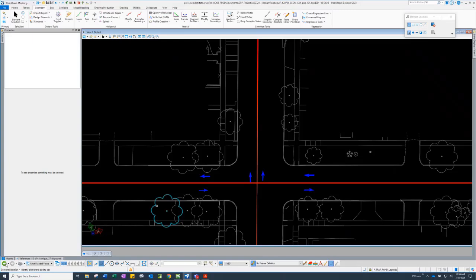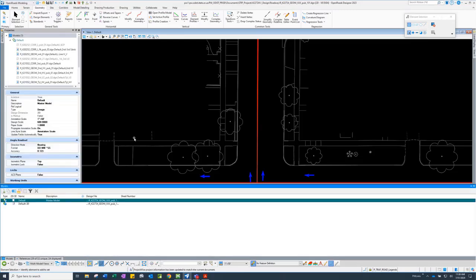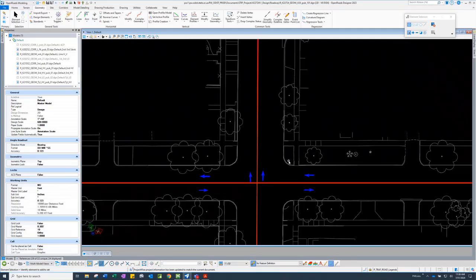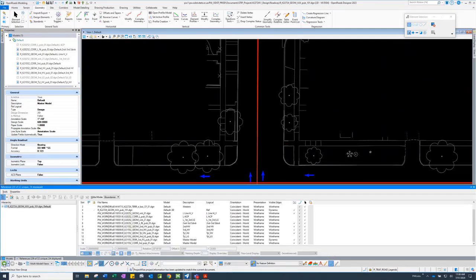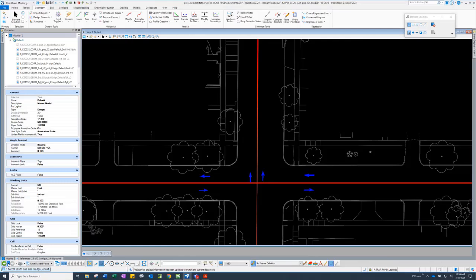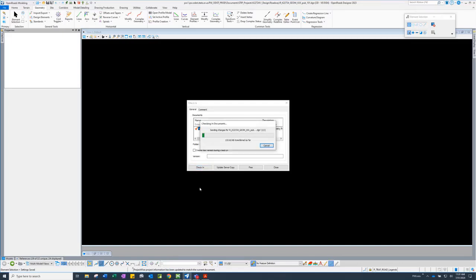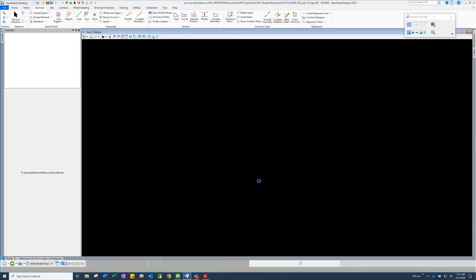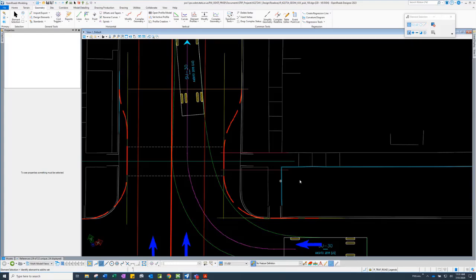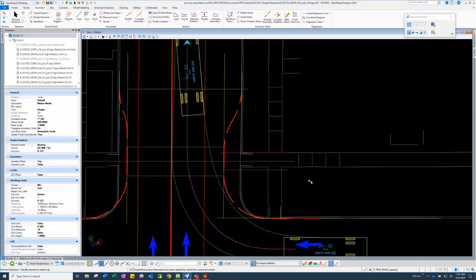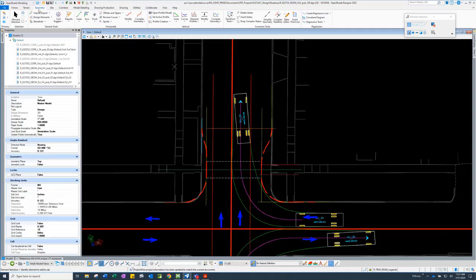And we see in the lower left corner a green circle with a white back arrow. If you click that back arrow, you can also choose, there's a pick list that's available if you go more than one, but most designers I know will do one change and that's about it because of resources of your computer. Anyway, hit the back arrow and see what happens. It will prompt you to check in the file that you just opened or free it, and it reopens the original file. Now, one of the things to note is I forgot to save my settings.